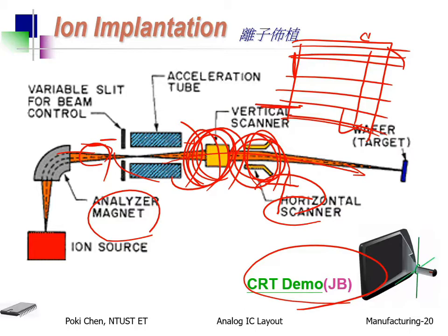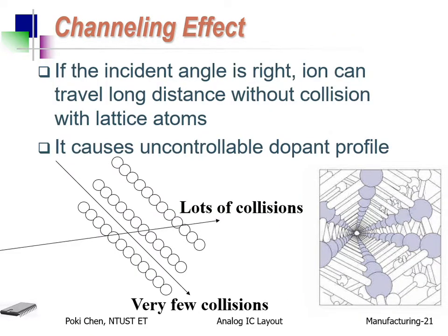So in this way, don't expect all the devices on the same wafer to be fabricated at the same time. No, sequentially. But we don't want to wait for a long time. The longer time you wait, the more systematic mismatch you need to face. That's it.